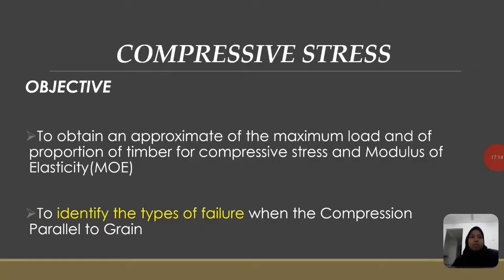Compressive stress objective is to obtain the approximate of the maximum load and of proportion of timber for compressive stress or modulus of elasticity (MOE). And then to identify the type of failure when the compression is parallel to grain.